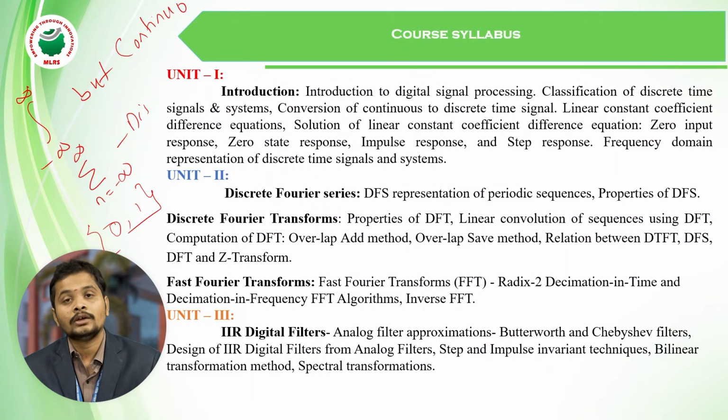Here we will know why we need the fast Fourier transform. Before that, the DFT requires many computations for a long sequence. If the number of samples in the sequence increases, it is not possible to compute such a number of operations. So coming to the fast Fourier transform, the number of computations is decreased compared to the DFT. And using butterfly diagrams, we will compute the given signal with the FFT.